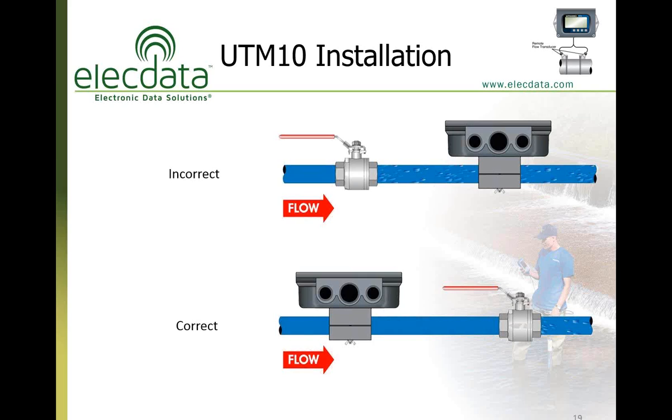This diagram shows the correct and incorrect place to mount the meter. Of course, we always want to make sure that we're upstream from valves, because they can cause turbulence and aeration inside of the line.